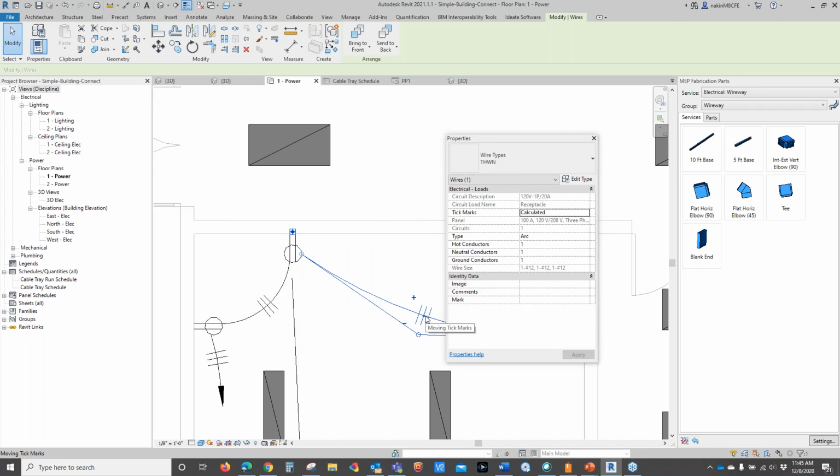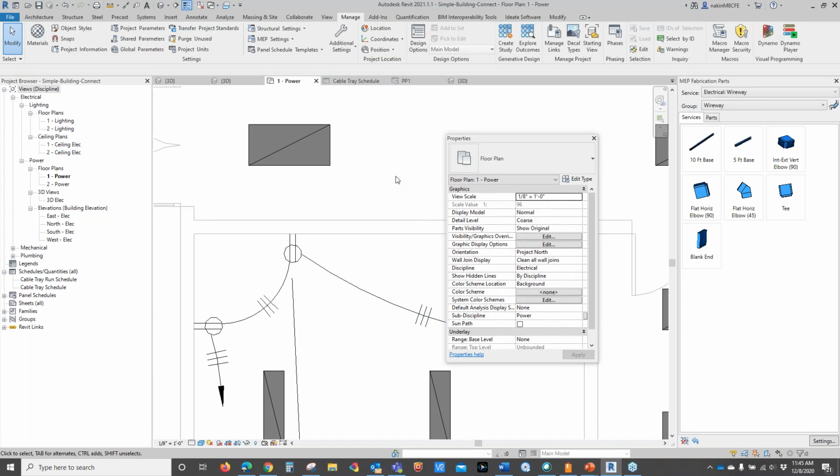Second question, is Revit 2021 lighting system still contained to only one switch per system? We routinely use three-way or four-way switching systems, requiring switching to use dummy switches which show up as unassigned. Unfortunately, yes, Revit 2021 still has the single switch system. I know that last week at AU, they were talking about adding that particular function into one of the updates coming up, but as of right now, it's still a single switch system.